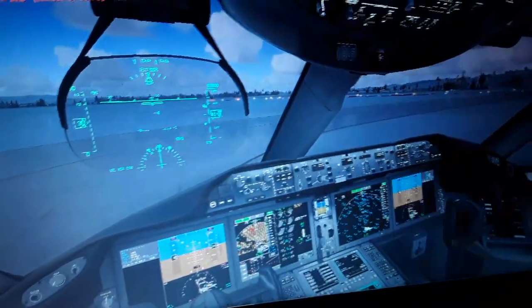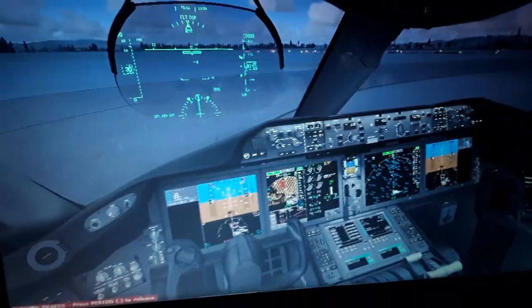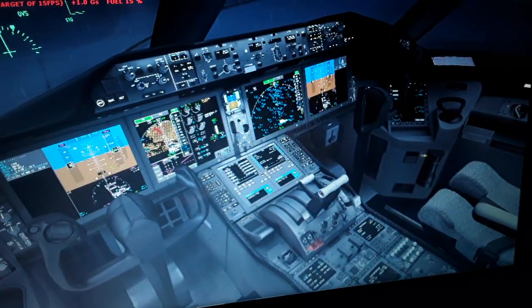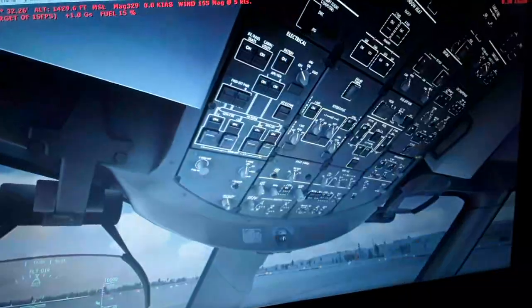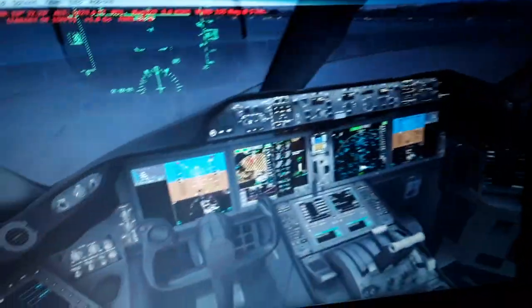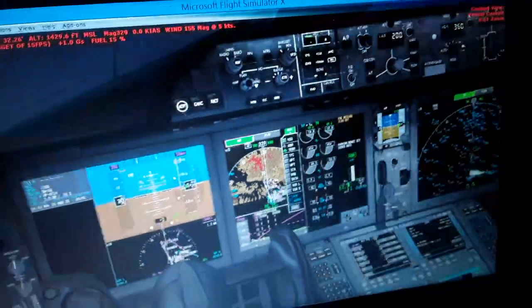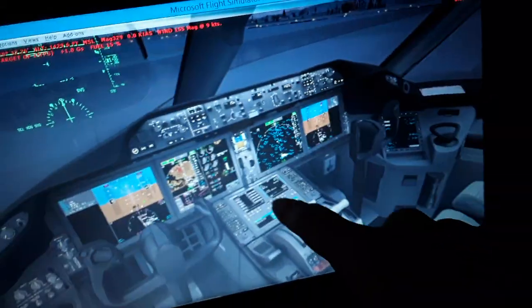It also contains the airspeed and air data computer for the airspeed and the altitude calculations, radio altitude, angle of attack of the aircraft as it flies through the airflow. This also has sensor temperatures and also laser gyroscope. So these are a few of the functions you can have from this air data computer. All these displays are very important. They feed other parts of the computer to the flight director system panel. So also the engine indications in the left and the right ACAS and indication across the system display. We have the left and the right.